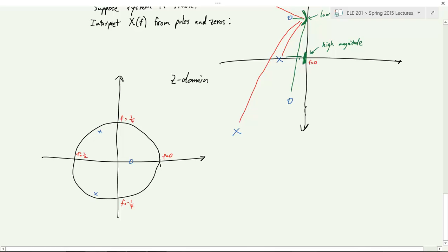What was that? Yeah, something up here around this pole. And so let's say we're approximating here. So we have to say, well, how much is that? You said maybe a third. Looks about correct. So in other words, we know that this Z transform has an inverse that has an impulse response that's stable. We could take a Fourier transform, and of course for discrete time, you only ever care about frequencies up to a half and negative a half, right?